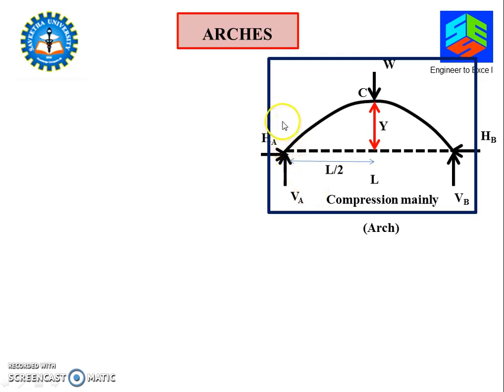Whereas an arch, in most cases, is considered a compression member only. Tension is the property which creates heavy headaches for structural engineers. In compression, it doesn't give much problem, because most of the construction we do is with steel and concrete, and both are very good in compression.